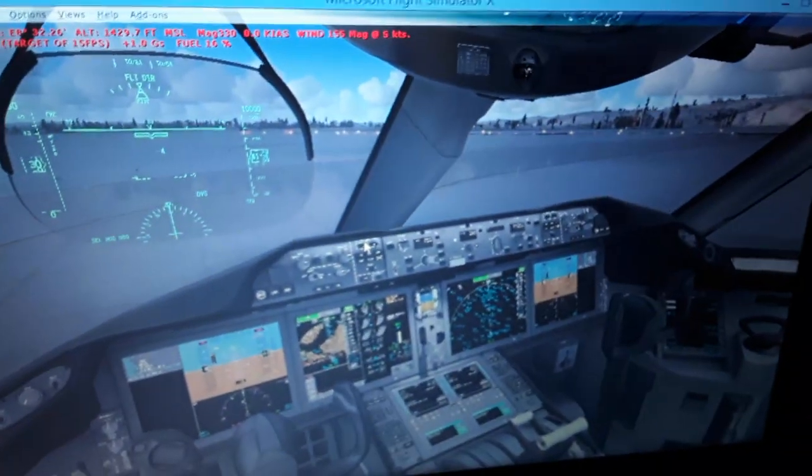rate of climb and descent of the aircraft in feet per minute. We also have the altitude indicator with the artificial horizon, the pitch ladder and the bank angle. The ILS localizer, we have the ILS localizer system, the instrument landing system that receives the radio